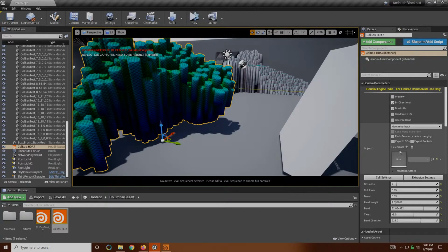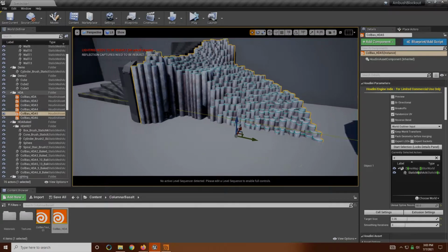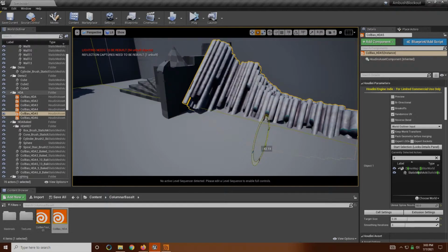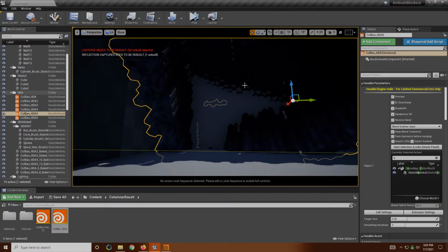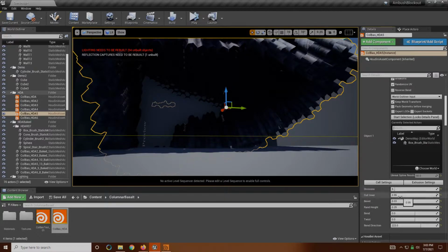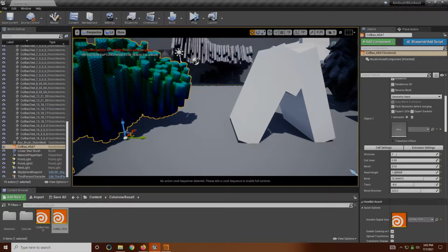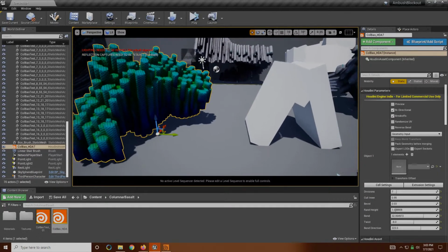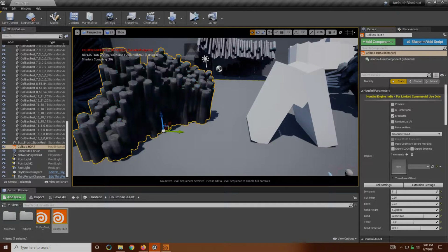And then the col inner, I'll show you in this one here. The col inner just controls how much of the geometry on the inside should get deleted. Since most of this extruded geometry isn't actually seen, I just delete that in the col inner setting. It just dictates how much of that is deleted. And then the last piece of functionality is that you can actually just use whatever geometry you want inside of UE4.